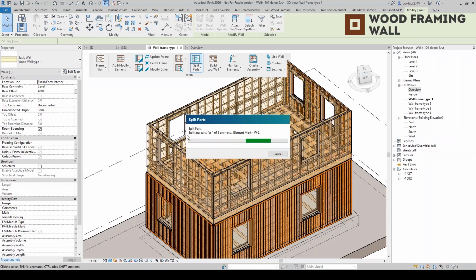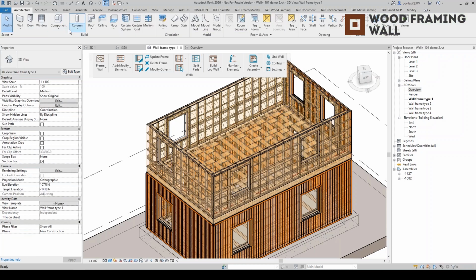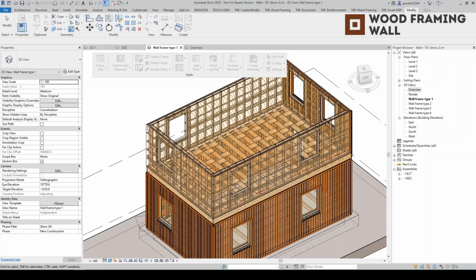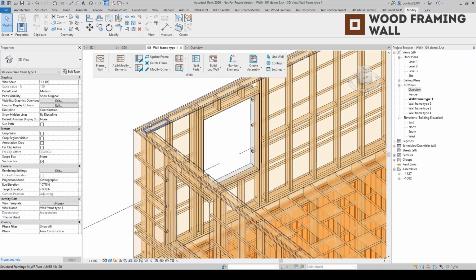Okay, it is also important how you connect your walls. So in this case, the walls are allowed to join, and I believe using this. If you go to the geometry tab here, you use this Revit function to define how the walls join. Okay, so you define how the walls are going to join, whether a mitre joint or a butt joint is going to be used. Ideally, it's a butt joint that we want, to be able to join evenly.